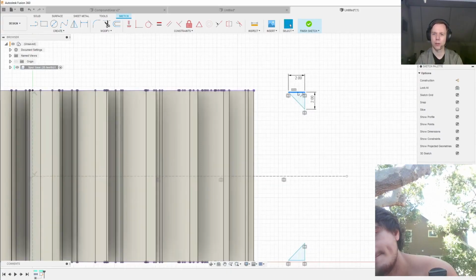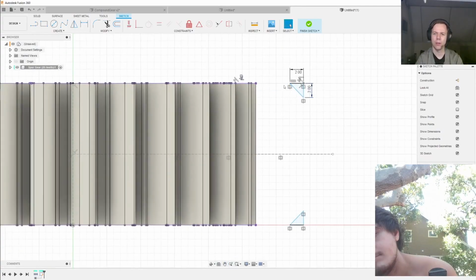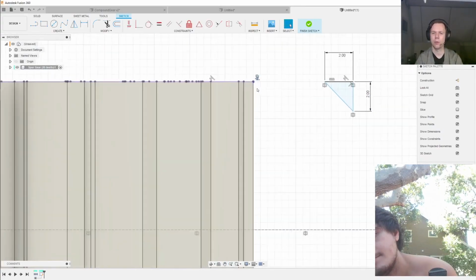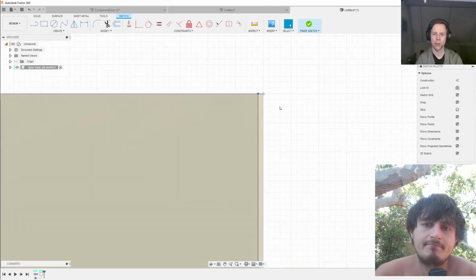So what I'll do first is select this top edge and select this projected line and make these collinear. And now the only degree of freedom we have left is this side-to-side motion. So one thing you could do is make this point coincident with this point. But if you zoom in real deep on this area over here, you see that there are in fact 2 points very close to each other. So you run the risk that you would select the wrong one.